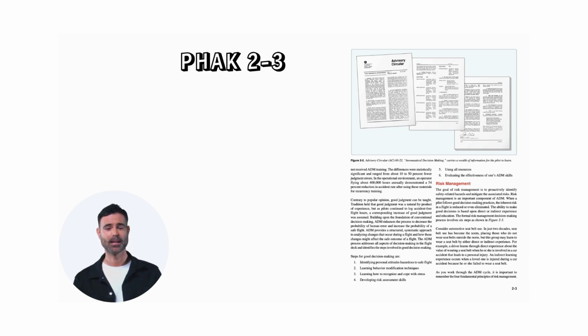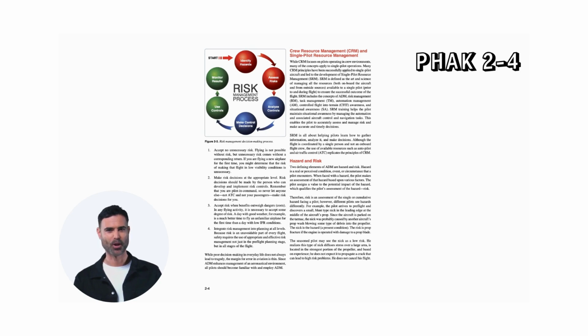An indirect learning experience occurs when a loved one is injured during a car accident because he or she failed to wear a seatbelt. As you work through the ADM cycle, it is important to remember the 4 fundamental principles of risk management. 1. Accept no unnecessary risk. Flying is not possible without risk, but unnecessary risk comes without a corresponding return. If you are flying a new airplane for the first time, you might determine that the risk of making that flight in low visibility conditions is unnecessary.